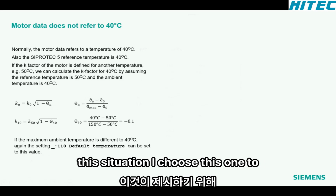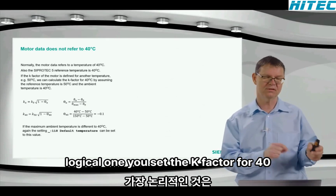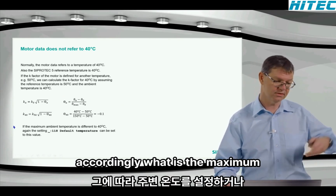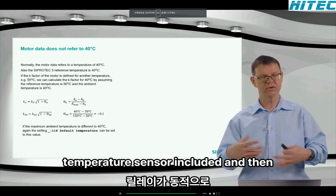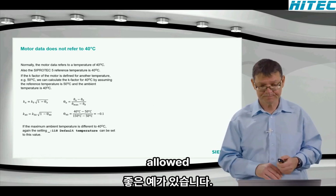I choose this one to present because I think this is the most logical one. You set the K factor for 40 degrees. You need to calculate that. And then you set the ambient temperature accordingly. What is the maximum temperature? Or you set here then the temperature sensor, include that. And then the relay will make dynamically the calculations, what is allowed or not allowed.